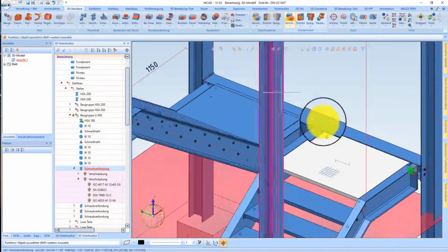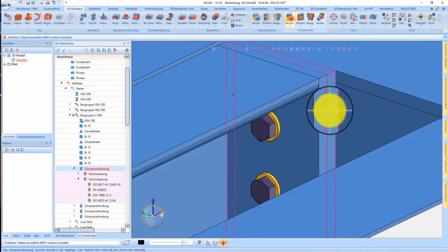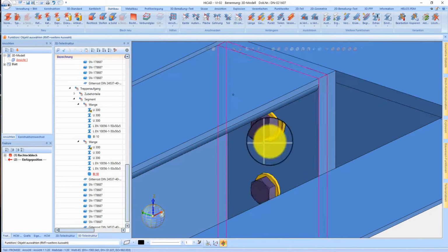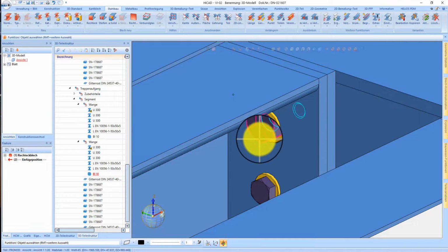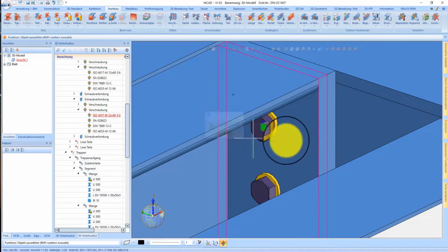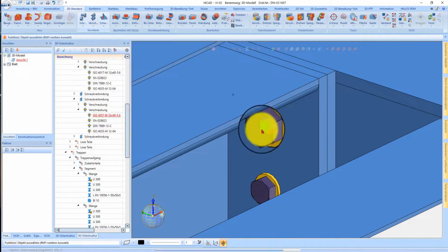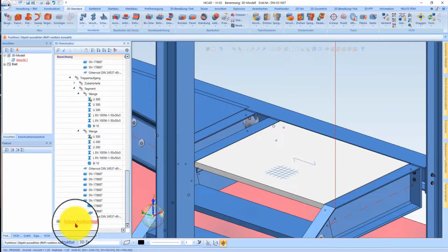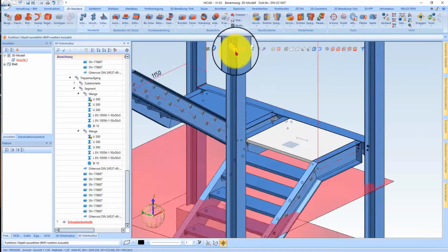Just by copying, this screwing, you can see it also on the parts. The screwing is there, meaning they are correctly recorded in the bill of materials, but these screws have not provided the sheets with any holes. That means I can easily check this here. I can say, show me the assigned parts, and there are 0 assigned parts. I would also have the option to request a parts check for the screwing itself. I will just do it. And it says, for example, that here, in this case, someone has created a part. I can say, only display the active part, which screws have no assignment here.